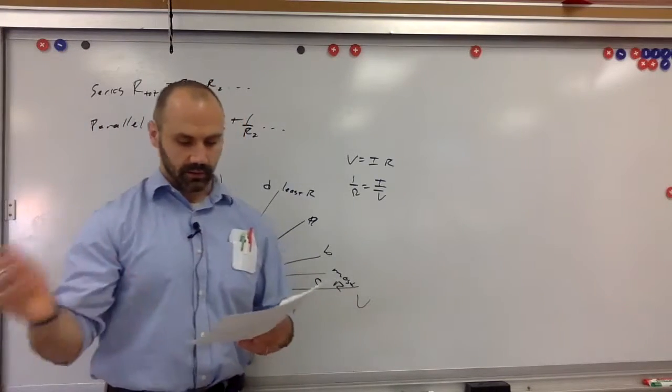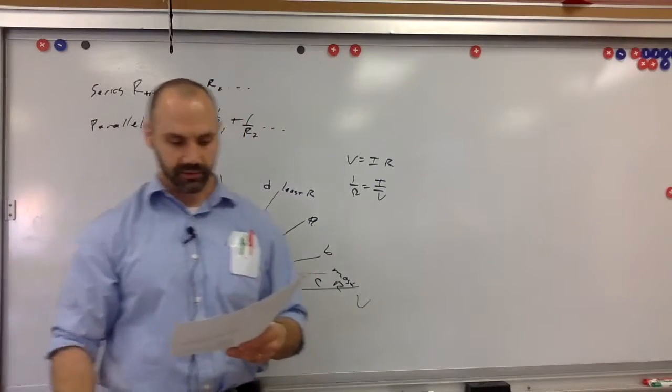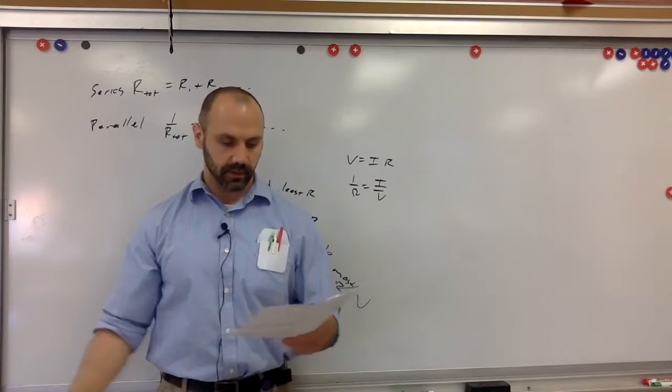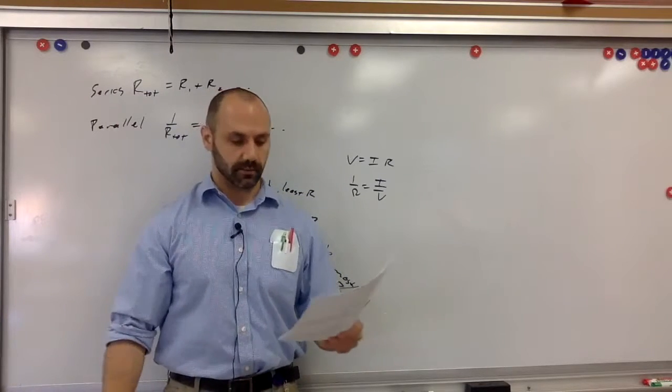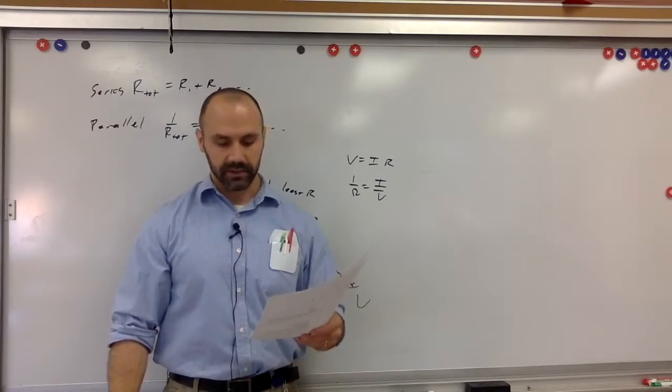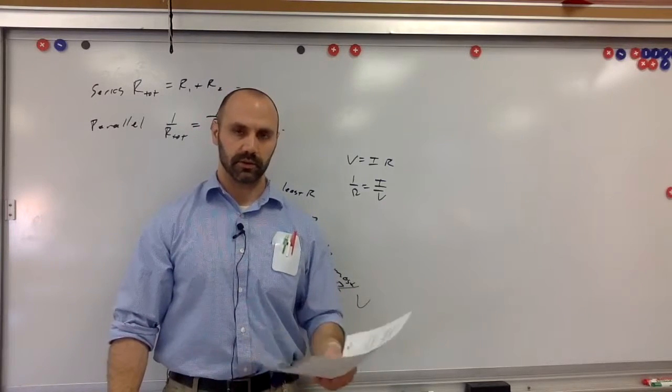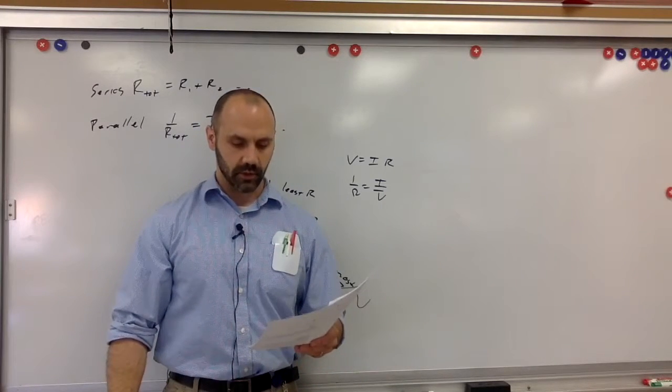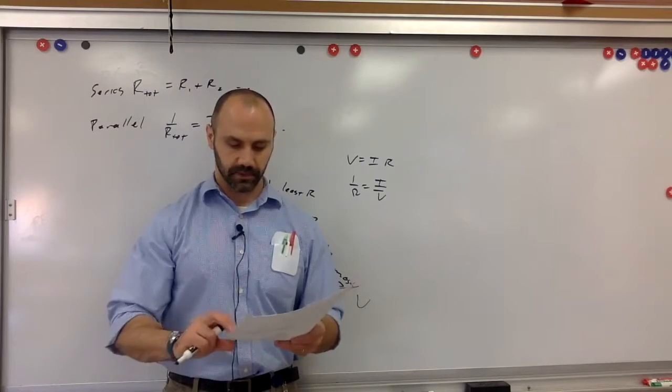Okay. And then the graphs to the right in example 2, the first one, letter A, that's ohmic because V equals IR in that. In B and C, V does not equal IR, so neither of those is an ohmic material or an ohmic device.